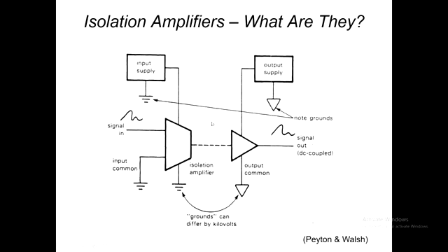And one thing that's important is to make sure that these amplifiers are powered by separate grounds. I've seen some interesting things done where some folks have gone to the lengths of putting in an isolation system to protect one side or the other, and then they've powered them both from the same power supply, which kind of ruins the whole concept in the first place. So it has happened, I've seen it, not very smart. Yeah, after all that effort.